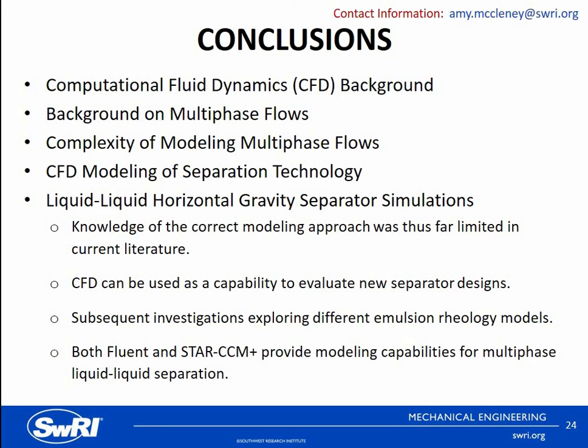So in conclusion, I went over some background information on CFD and why it's important, and some background information on multiphase flows and why modeling multiphase flows is extremely complex. I then went into some information on design of separation technology and some CFD modeling approaches for separation technology, and then showed you some examples of liquid-liquid horizontal gravity separator simulations that we conducted here at SwRI.